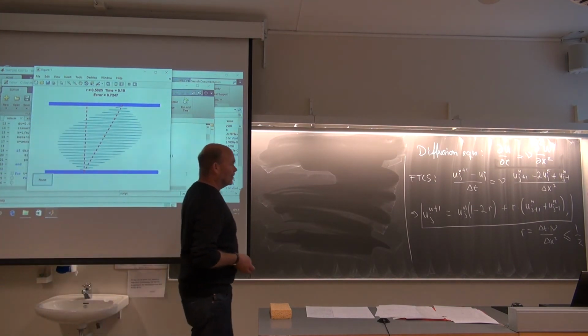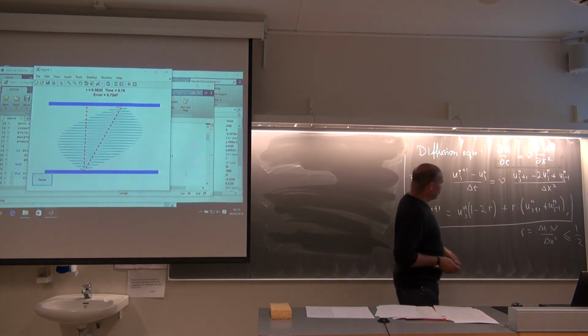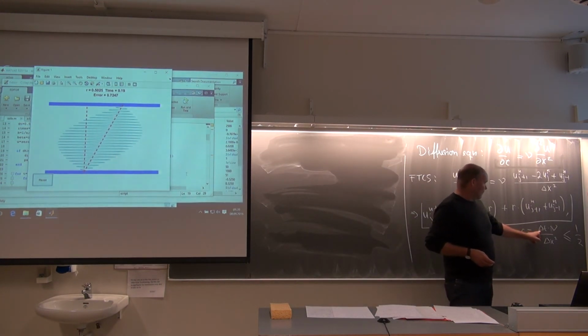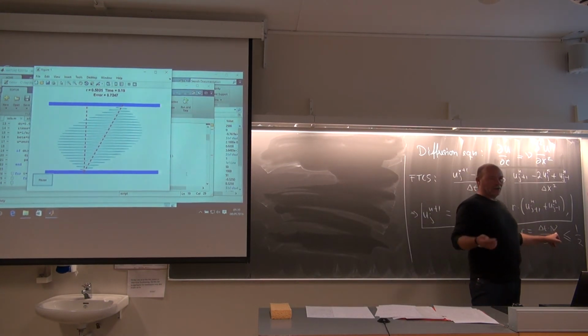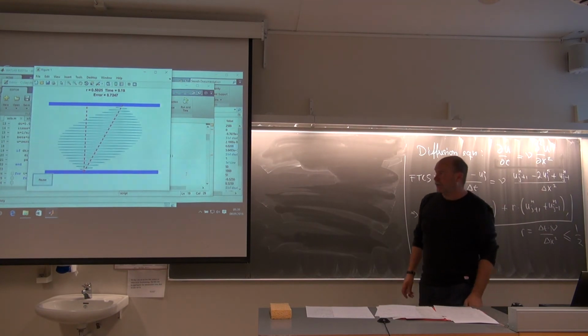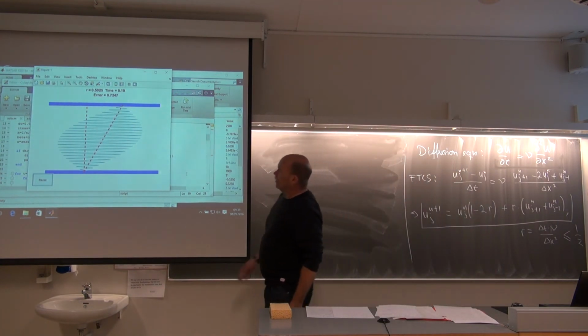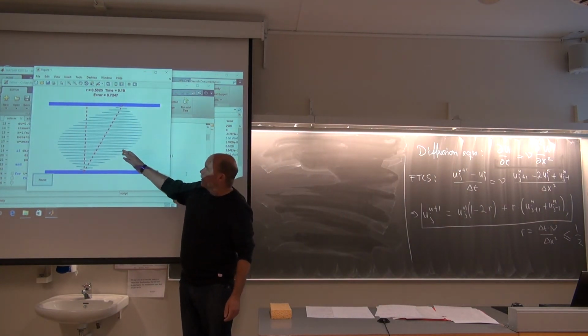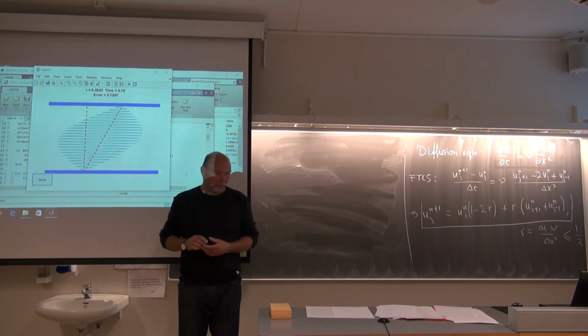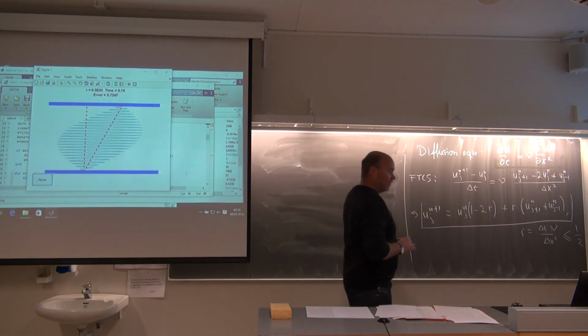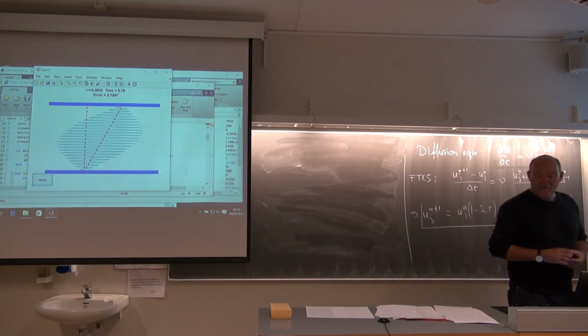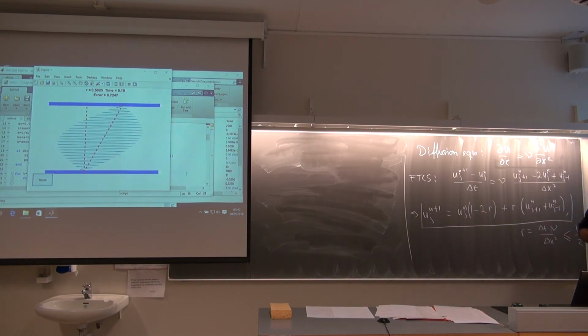It means you will have very, very small time steps, of course depending on the viscosity or the Reynolds number in your problem. But here you risk using very, very small time steps. As you can see here, just for this simple problem with startup of a Couette flow, you have to use a very, very small delta t to be able to have a stable simulation.